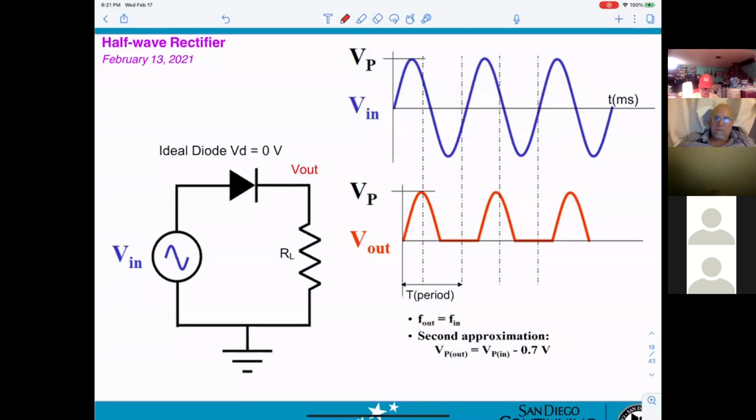They rectify only the positive, so therefore it's only half the sine wave. Halfway rectified. You see the sine wave, you get positive alternation, negative alternation. However, they rectify only the positive in this case. The negative not. Only positive can be rectified.